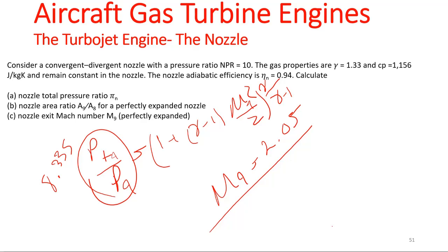Can we apply the conservation of mass? Yes, right. Conservation of mass essentially relates your m dots, and in your m dot, your velocities and the density are included. Using the ideal gas law, you can include the pressure and so on. And we are all dealing with pressure ratios and the temperature here.